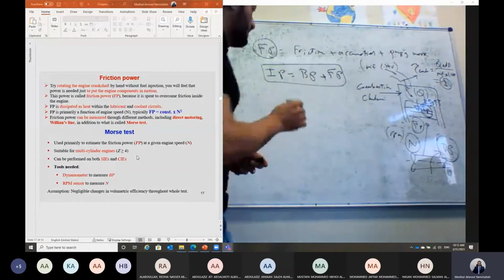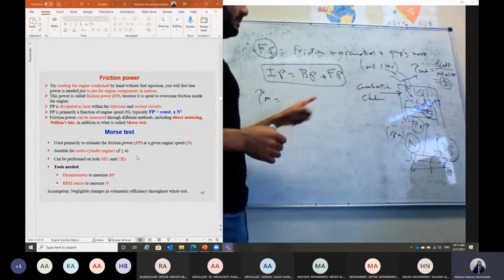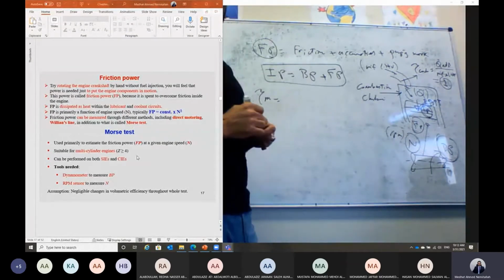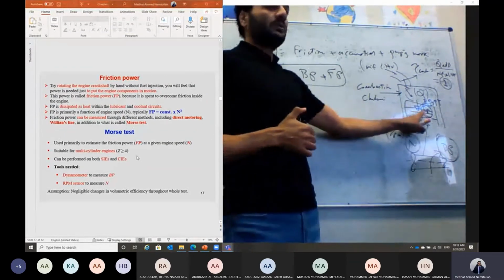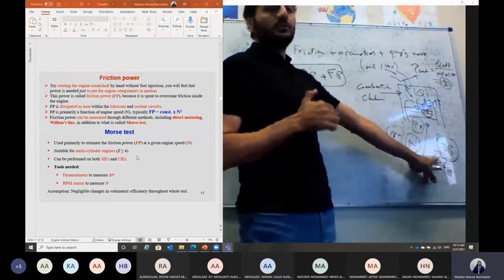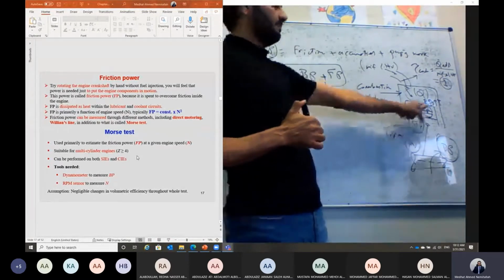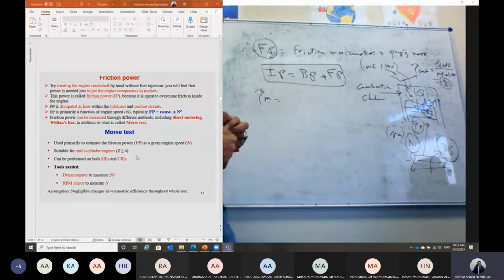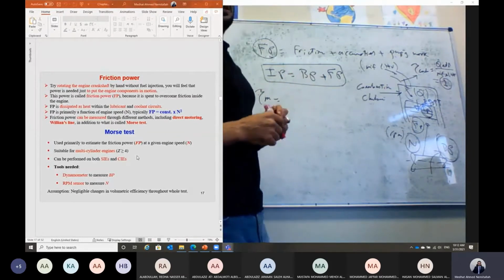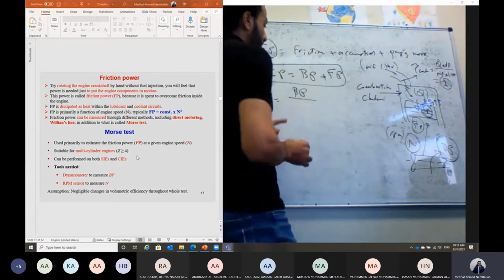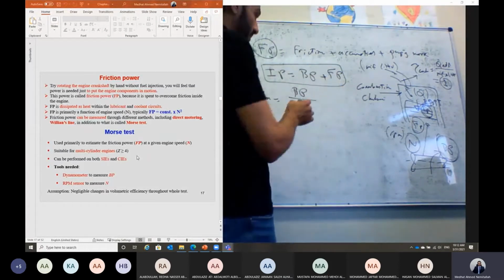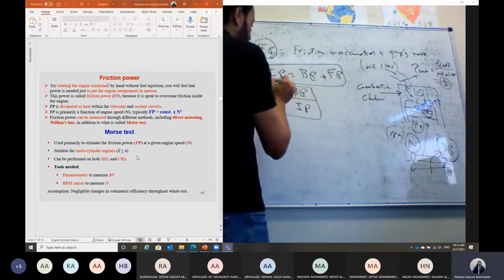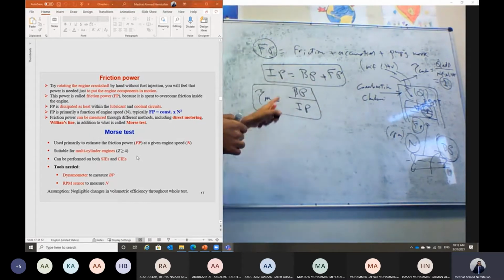And we have related, Shabab, also the brake power and the indicated power through the mechanical efficiency, because indicated power is a mechanical power. Brake power is also a mechanical power, but indicated power results actually in reciprocating motion. Brake power is actually just a rotary motion. When you convert from a mechanical power to a mechanical power, we have to define a mechanical efficiency. And this mechanical efficiency will give us an indication about the friction loss power, which is equal to the brake power divided by eta mechanical. For the engine, it is the ratio of the brake power divided by the indicated